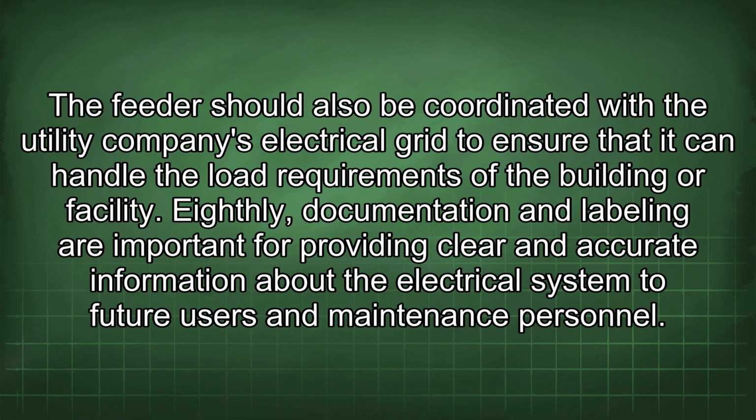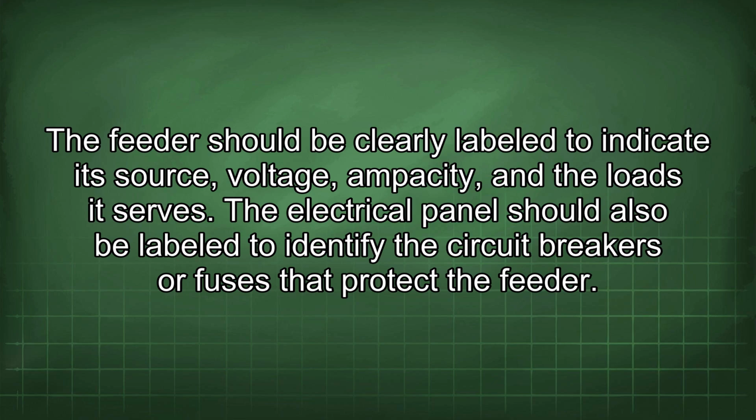Eighthly, documentation and labeling are important for providing clear and accurate information about the electrical system to future users and maintenance personnel. The feeder should be clearly labeled to indicate its source, voltage, ampacity, and the loads it serves. The electrical panel should also be labeled to identify the circuit breakers or fuses that protect the feeder.